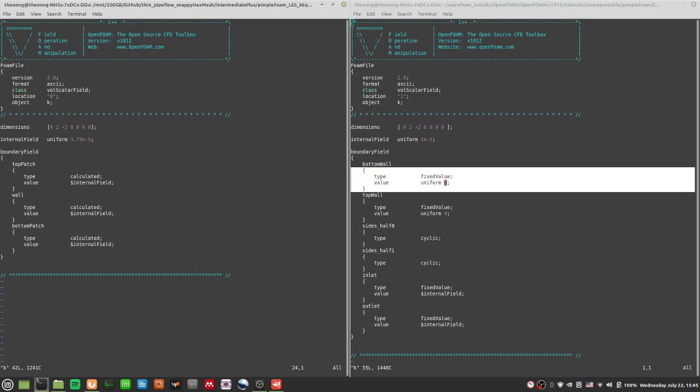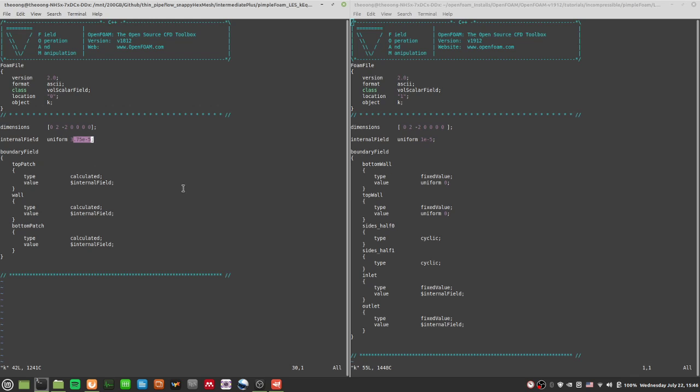So maybe one of the easy ways is to take the value you would normally use if you have a k-epsilon model. You have a kinetic energy k there. You use that value and you divide by 5. You'd roughly be in the ballpark of where your turbulent kinetic energy is. That's an easy estimate anyway. Let me put it into the comments here. I may or may not be right, but this is where you can start off.